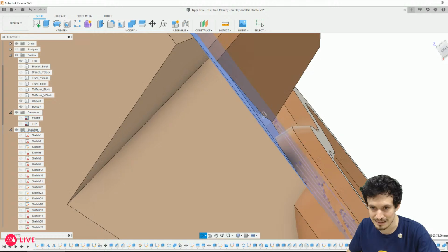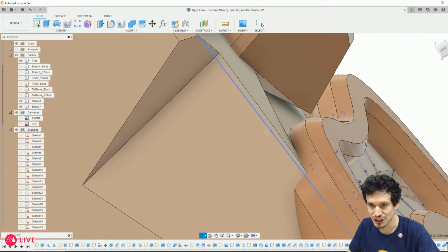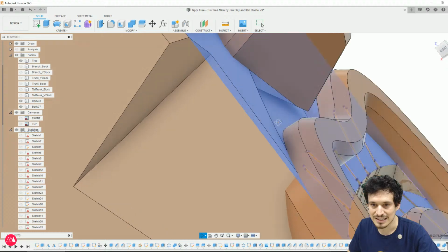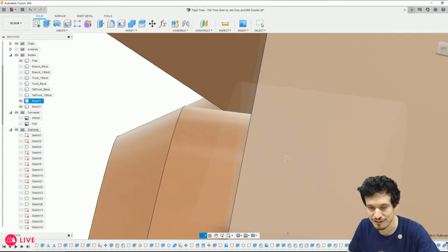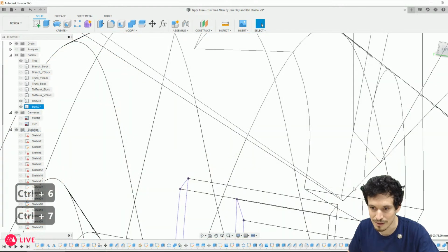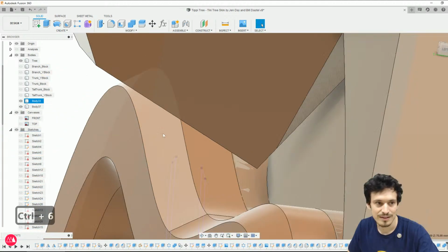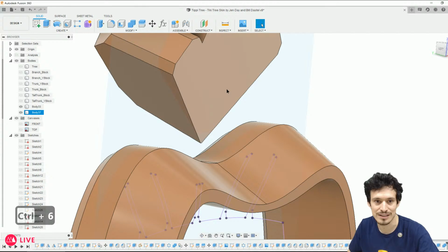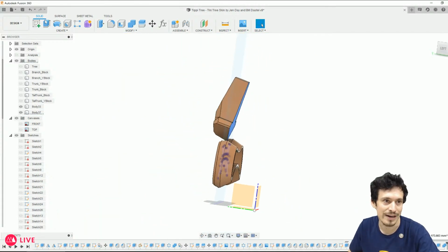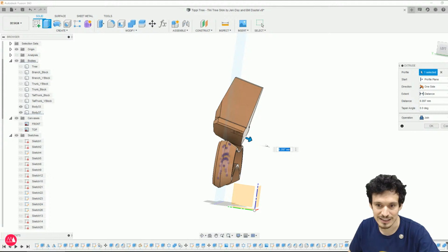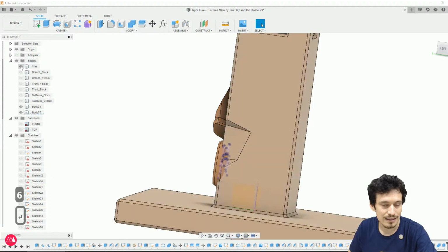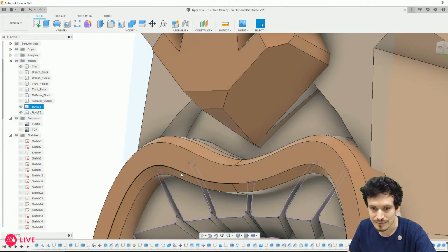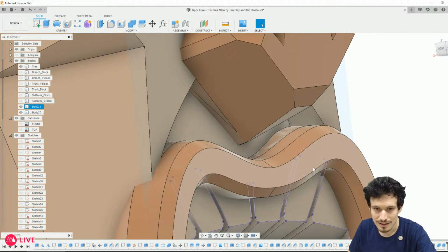Whoops. I did mess up a little bit. There's a gap there for sure. That's because the nose wasn't designed for this. Okay, no problem. I think I can still select that face. Can I? Hold on. Let's hide the tree. I just need to extrude this nose backwards into the face a little more now since we cut away from it. That's actually all we have to do. Extend that like 6 millimeters. There we go. I think that's pretty good.